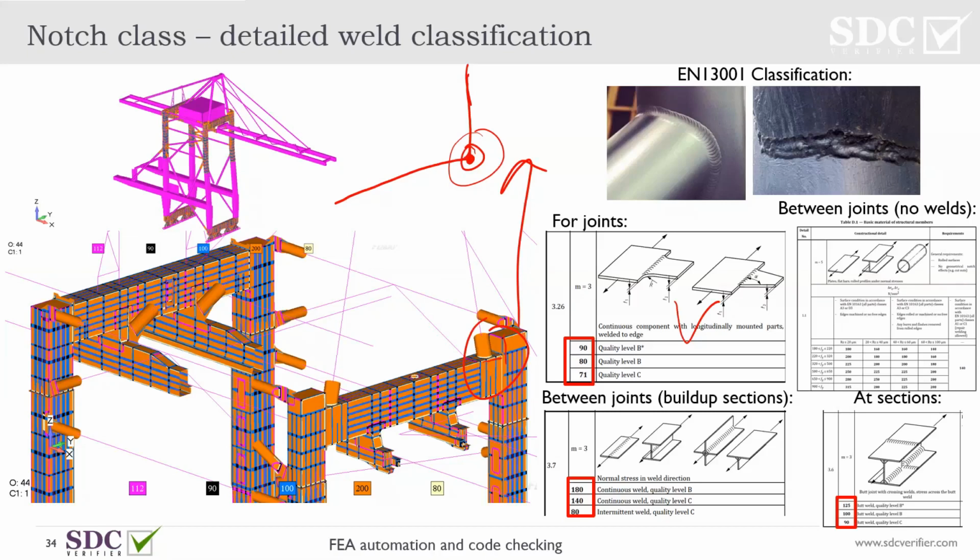You should never neglect that. So our suggestion is this approach replaces stress concentration factors because you simply pick them up with the model, and if you apply accurate classifications, then that's a pretty much accurate situation. That's one thing about the hotspot stress method.